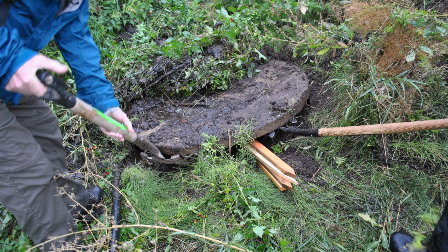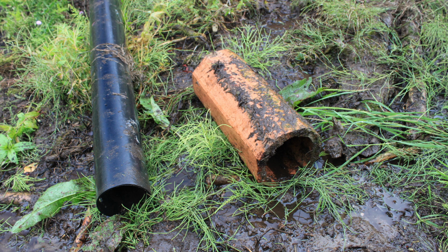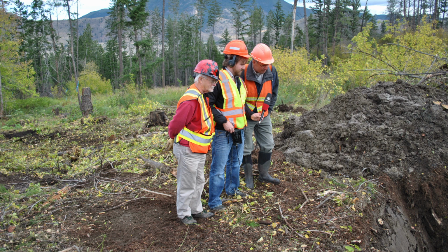The wells, well covers, and the pipes showed us that ranchers had been drawing water from the springs over many years. We found plastic pipes for moving water and clay tiles for drainage, all of this while designing the wetlands. I should have known we would need to armor with rock the inlets and the spillways for the wetlands we wanted to build. This is because of the steep slopes, the sandy texture soil, and how fast water enters each test hole that we dug.